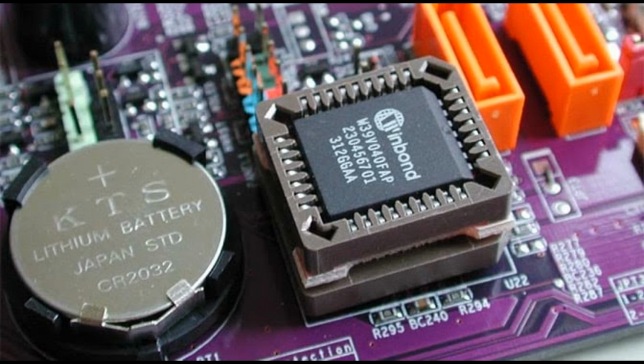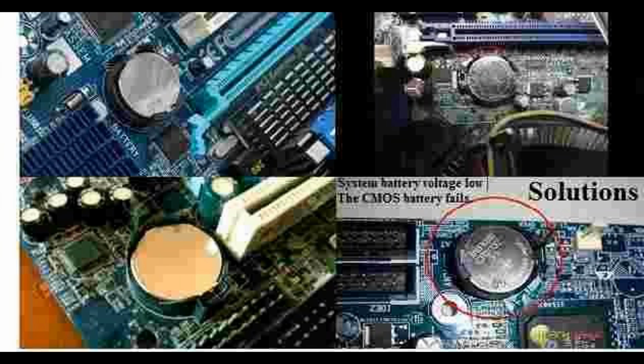Complementary operation refers to the behavior of complementary metal-oxide-semiconductor (CMOS) circuits, where both N-channel MOSFETs, NMOS, and P-channel MOSFETs, PMOS, are utilized in tandem to achieve efficient digital logic operations. In CMOS technology, NMOS and PMOS transistors complement each other's functions, allowing for the creation of highly efficient and low-power digital circuits. Here's how complementary operation works.